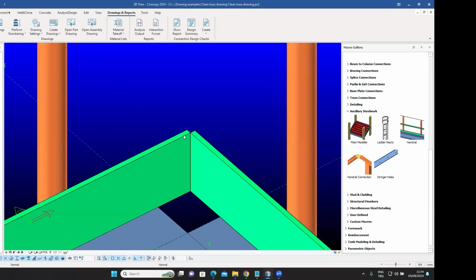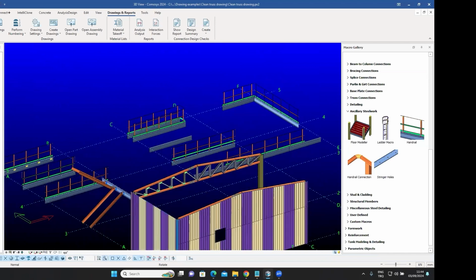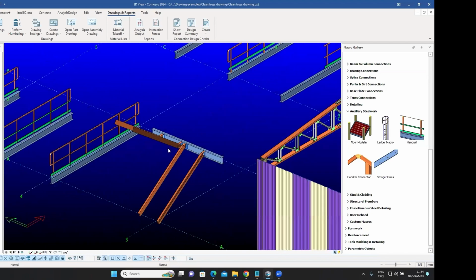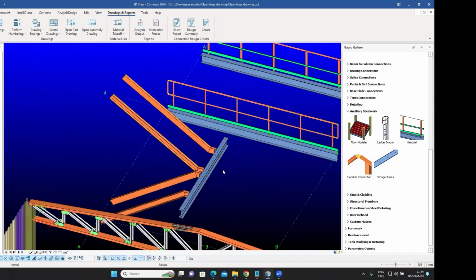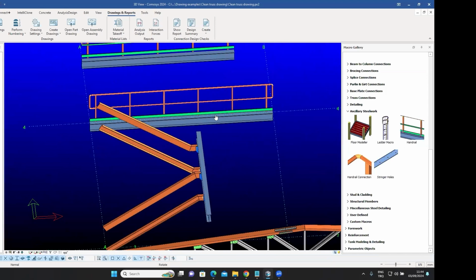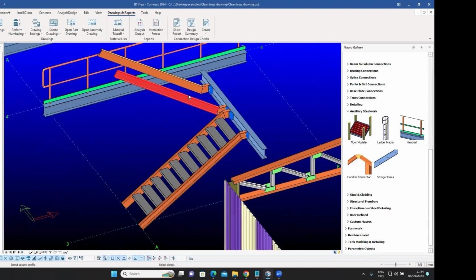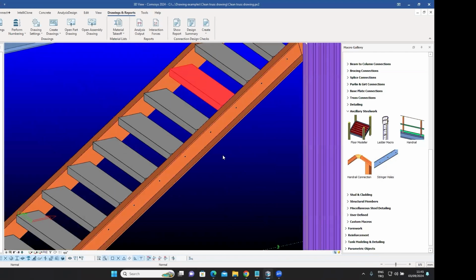Now, let's do some other cases. What we can do is, for example, we have a little staircase over here. And in the stack, if I've got two stringers going up and then two stringers going further up, let me just create a few stringers, for example. Let's say this one, and I create some stringers. There are some threads. I've created some threads. This one, I basically use this stringer holes macro. It not only creates the holes inside the stringers, but also creates the threads for you.